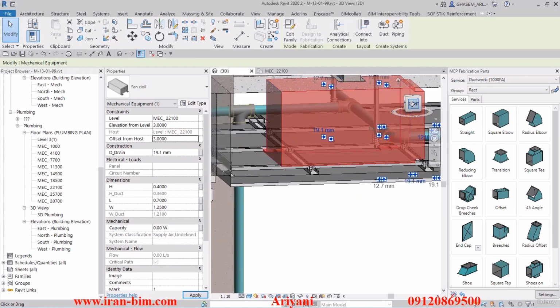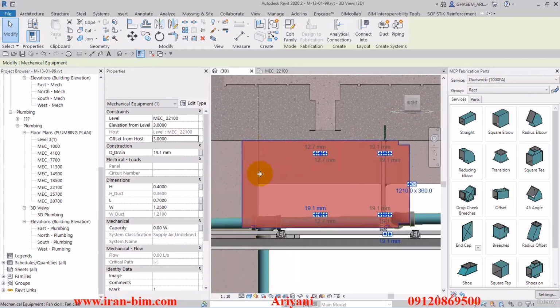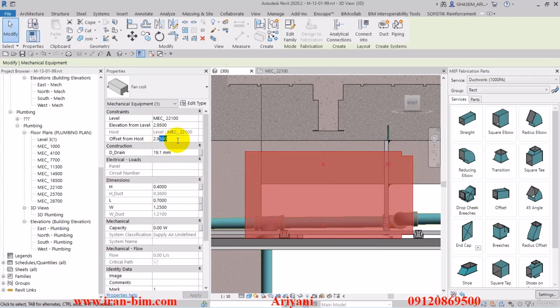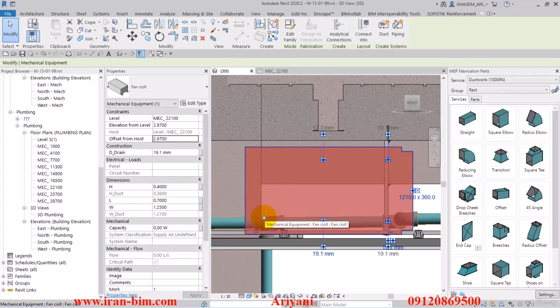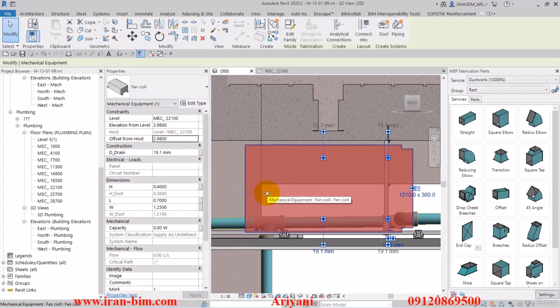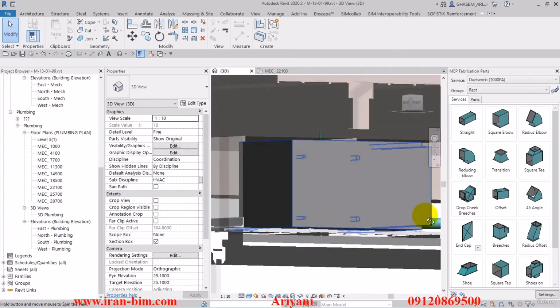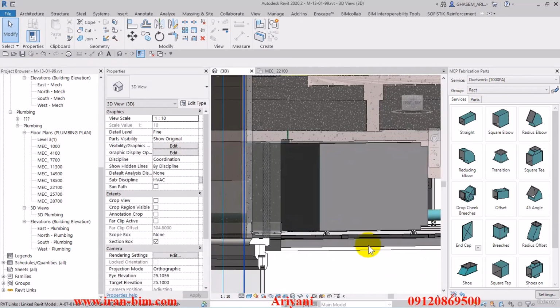So I'll change the offset to 3 meters and then go over to the front view. Now it's practically connected to the ceiling. Let's move it lower, put in 2.98. First 2.95, then 2.97. All right, put in 8 and let's see. All right, change it to 2.99. And there we go. And as you can see, we're using as much space as we possibly can.